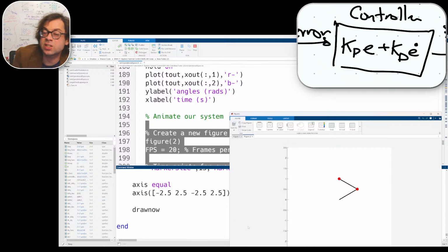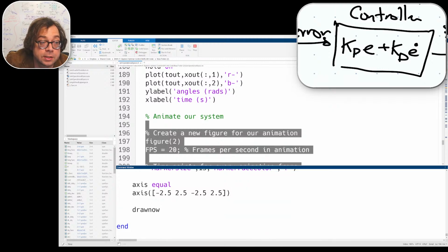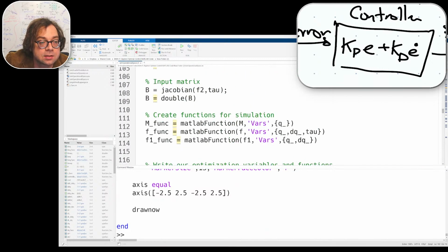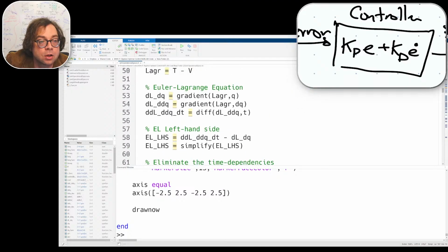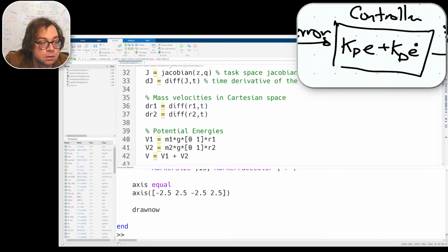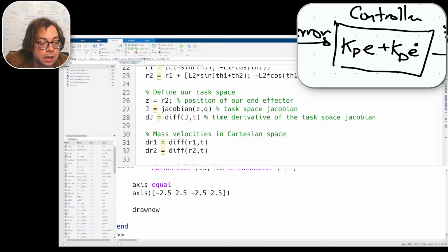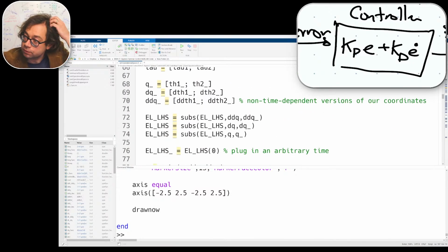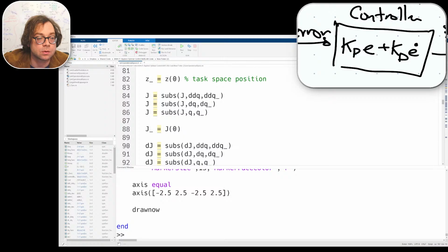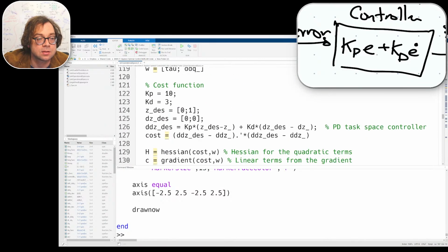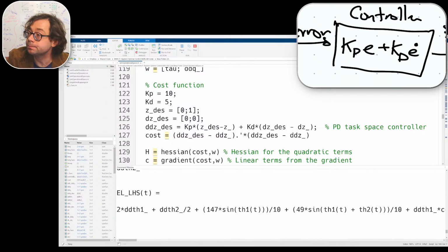Beautiful. You'll notice it overshot a little bit. That's just because we arbitrarily chose these gains here. Oh my goodness. We did it. And it will still work even if we add weight to it. Where are our gains? So if there's overshoot, and you learn in controls 1 that if you have a derivative gain, that's like a damper that slows things down. So let me make that bigger, make that 5. And that should hopefully run in a different way.